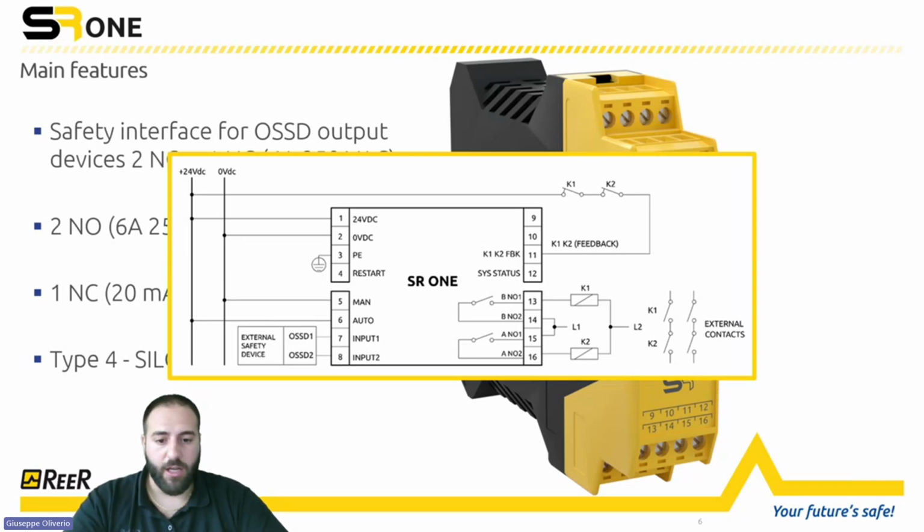Like other interfaces that we have in our portfolio, we can connect the normally closed contacts, so the feedback contacts, directly to pin 11. So the module itself is in charge of checking the feedback contacts and the switching of these feedback contacts based on the inputs and based on the time. Here on pin 7 and 8, you can see the OSSD inputs.